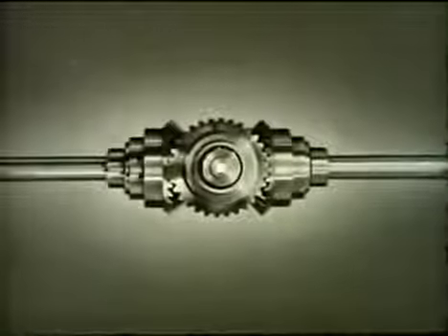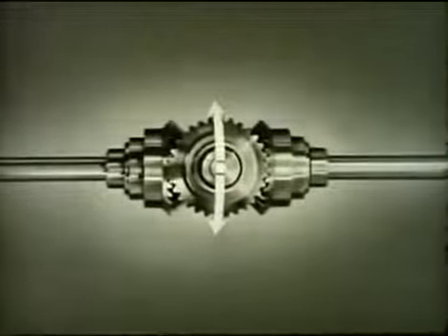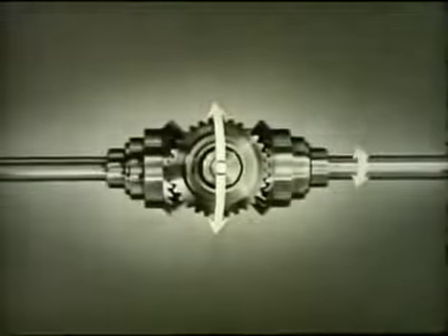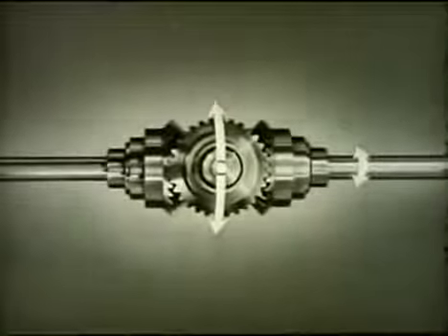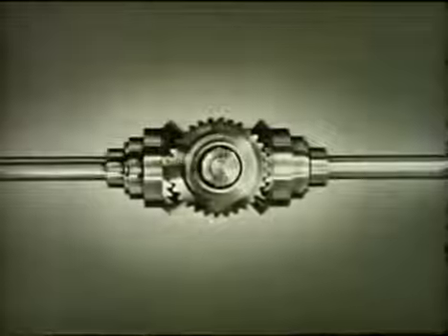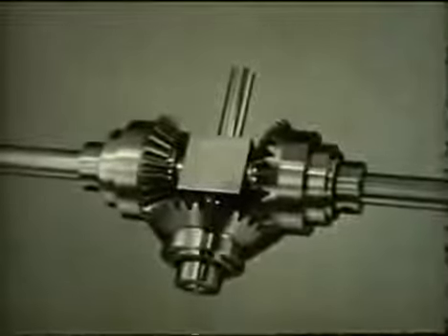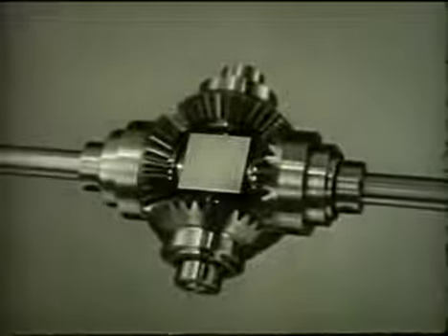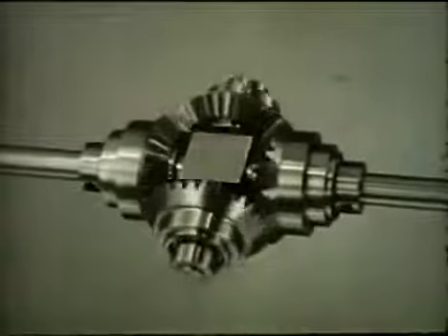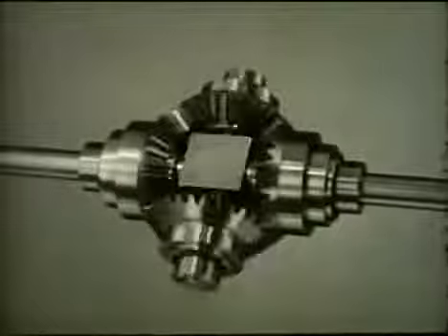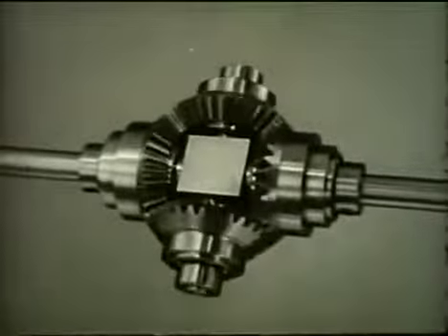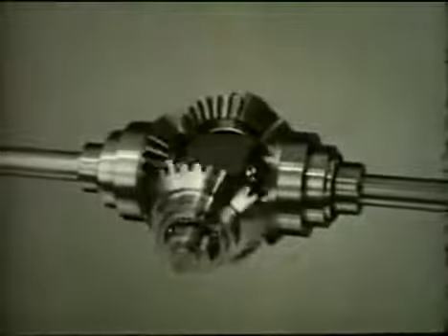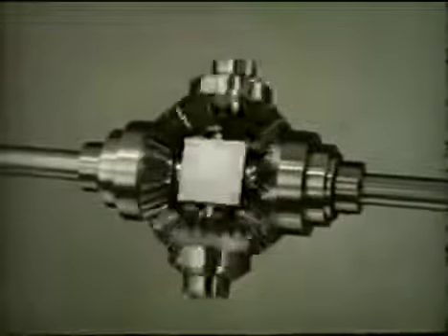Movement of the spider gear center along its circular path is delivered as rotation of the spider shaft. Adding the second spider gear to balance the mechanism, we now have the complete differential. It should be remembered that the output may be either one of the end gears or the spider shaft. The other two then become the inputs.